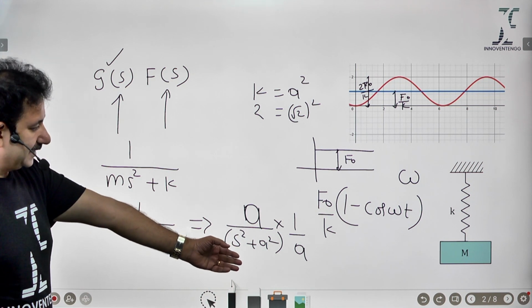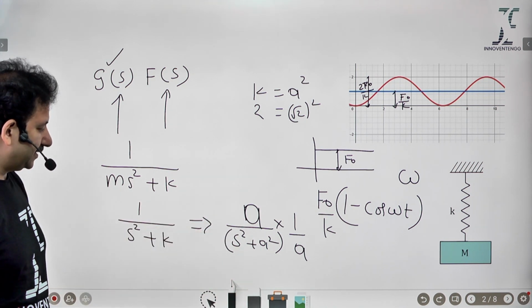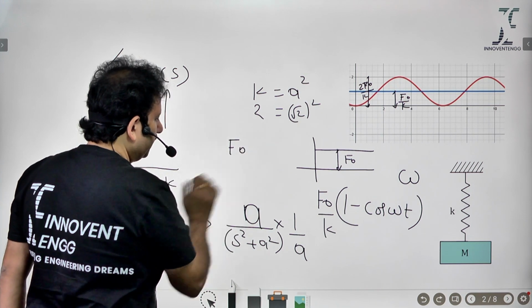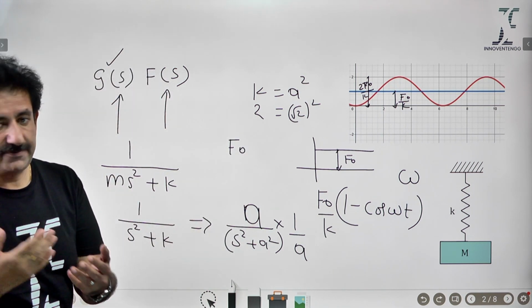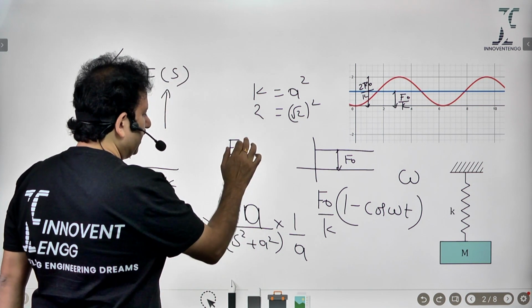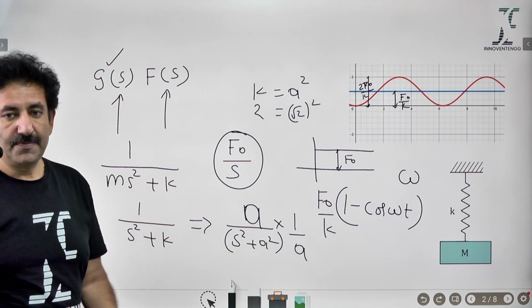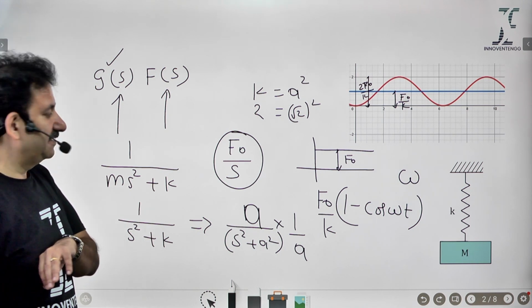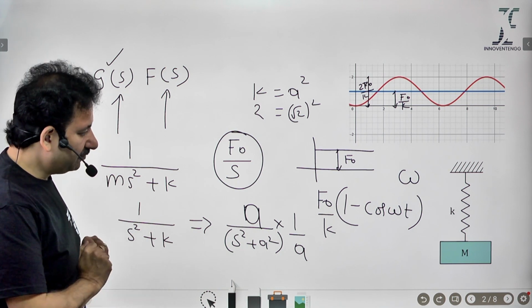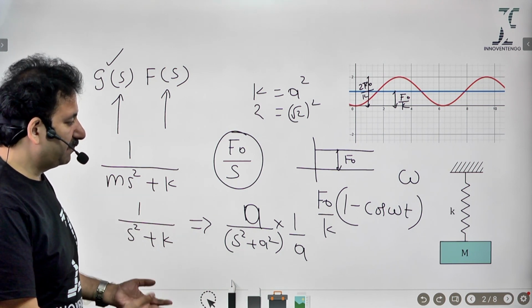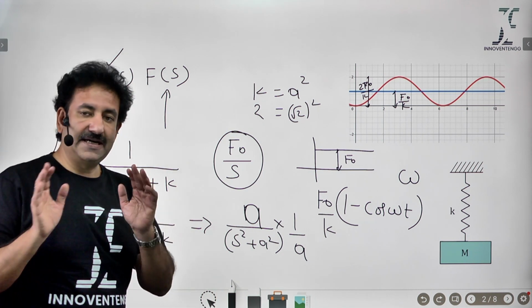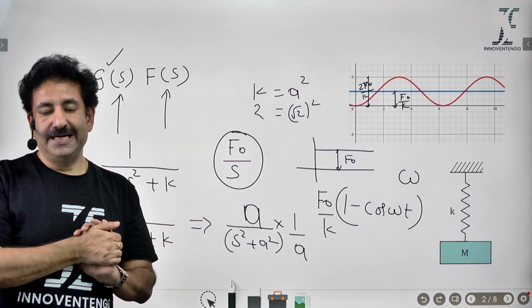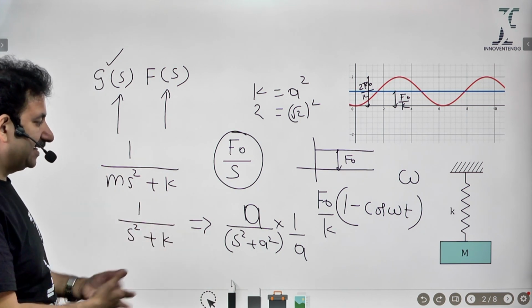So this is easy to get. This is the standard transfer function of a physical system, a spring mass system. Now I need to know the Laplace transform for the input. So the input is a constant F0. And if you take the Laplace transform of any constant, it is commonsensical that you get F0 by s. We have proved this umpteen number of times, because it is like integrating e power minus st into 1 into dt from 0 to infinity, which obviously gives you 1 by s. So now I don't have to do any solution of the differential equation or find particular integral, complementary solution, nothing. I have a ready tool called the convolution theorem. That is the advantage. Mathematics must always be used to apply in a physical situation, to get insight into a physical situation.